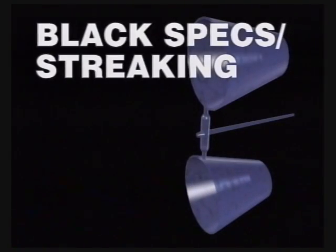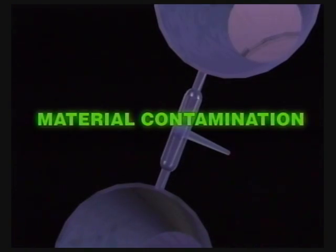Black specks or streaking in clear material is caused by material contamination. Purging of the barrel after using a dark material will help to avoid contamination problems. To completely purge the system, pull the screw and clean the screw and barrel by hand.